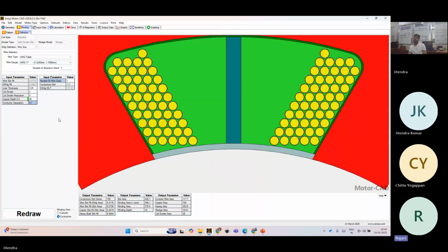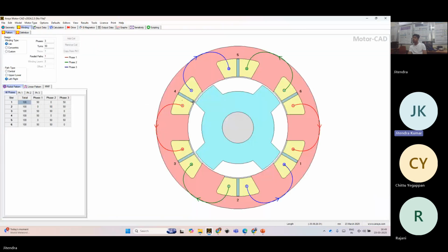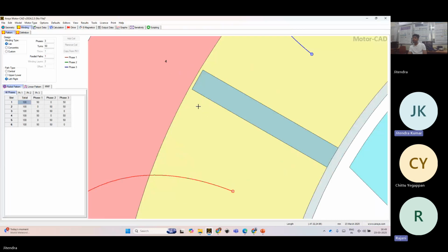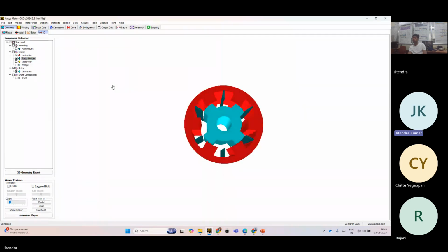And we'll take the coil divider. I never actually put one. I used to see a coil divider, but it's not there in real construction, so we never prefer it. Even in my design we haven't used a coil divider. Ideally people might use a stator divider, but a slot liner is sufficient, sir. For the slot liner we can give 0.78.